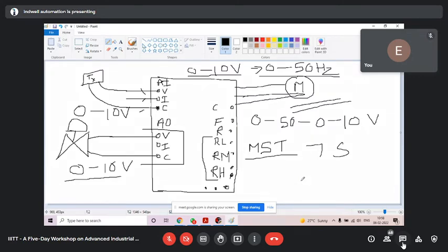Okay, now I come to the common uses of AC drive, or you can say the common control of a motor through AC drive. First control, very common control we take from this is frequency control, speed control. Speed control is frequency control. As frequency is controlled, its voltage will also be controlled. It's not like only frequency will be high low, but voltage will also be high low.